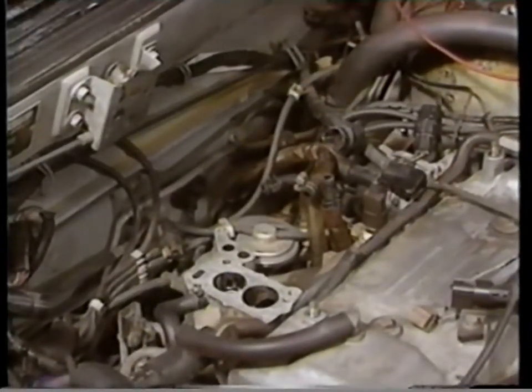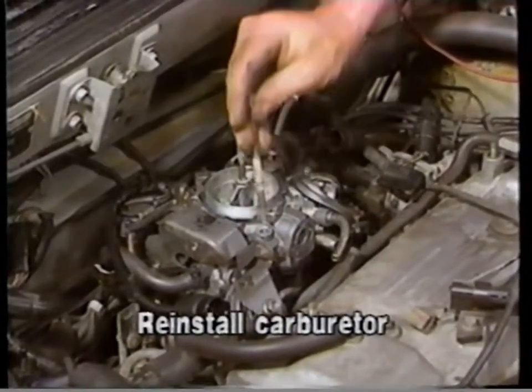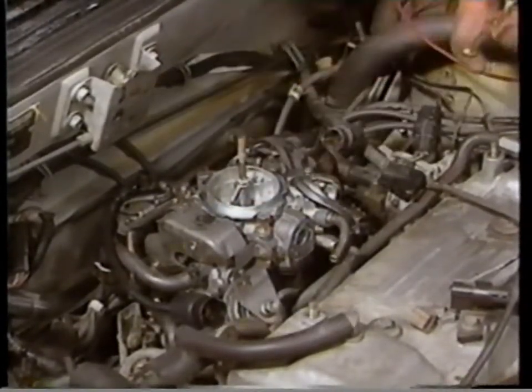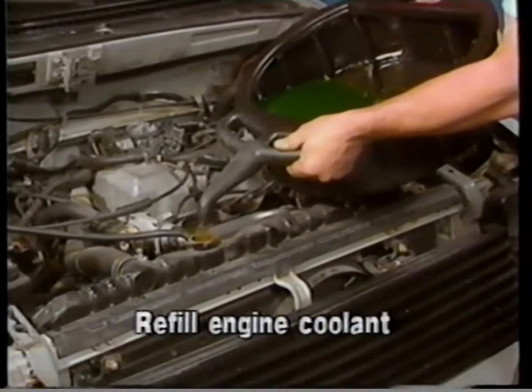Next, install a new carburetor gasket from the parts package and reinstall the carburetor following the applicable service manual procedures. Be sure to reinstall the throttle return spring. After reinstalling the carburetor, refill the radiator with the original coolant.